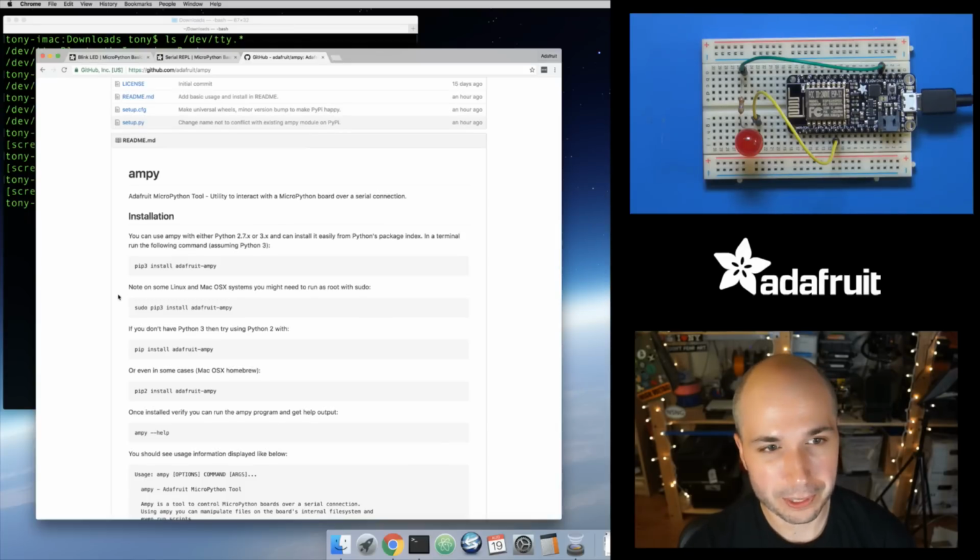The really cool thing is, if you want to manipulate those files in your Python code, you use the normal Python functions like open, write, and read. The exact same stuff you would do on your desktop works on MicroPython, which is really cool and powerful. We'll see this a lot more in the future. It's a big difference from Arduino, where if you want to load a file, you probably need to add an SD card and use the SD library, and it gets a little tricky.